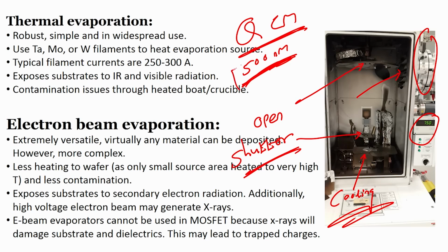When the film of our desired thickness is reached, the shutter will get closed, right. So, QCM is an extremely important tool used within the e-beam evaporator or PVD in general, to understand how much thickness of the film has been deposited, alright.